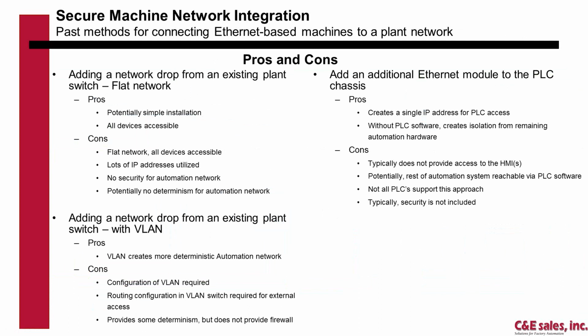That's not always the case. Siemens has several Ethernet-based communication processors that install on the chassis that are secured, such that you could turn on a firewall. So that is possible, but that's not common across the industry.